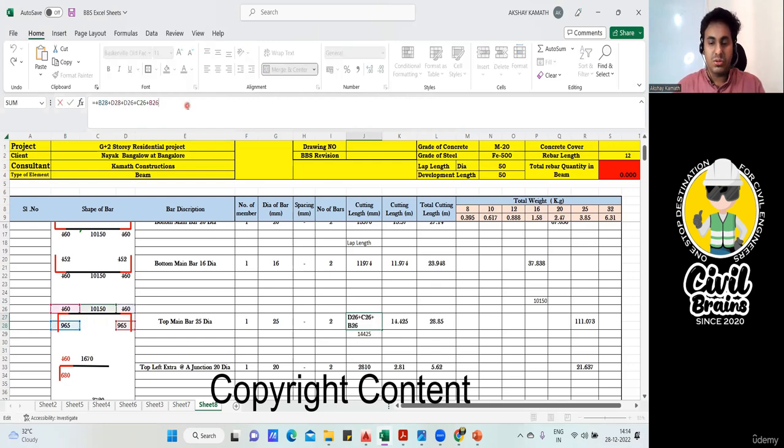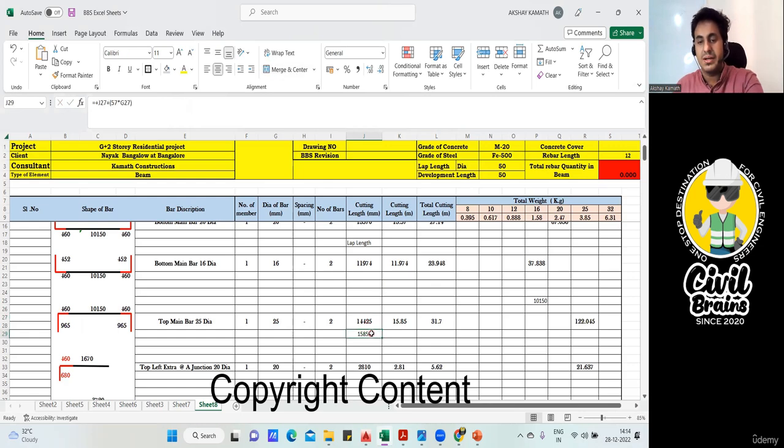So what I'll do, I'll say plus, open the bracket. One lap length is how much? It should be equal to minimum development length. So my development length is 57 into diameter of the bar, which is 25. Close the bracket. So this will be a total cutting length. Got it? Yeah, that's it. So I'll delete this, not required. And now this is my total cutting length.